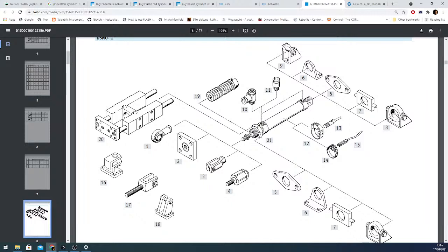Do we need those? Do we need an extra sleeve on the cylinder for dust protection? What kind of couplers we are using for connecting the piston rods? Do we need ball bearing variation for the connection? Do we just use a flange here, or cylindrical mount here, or straight mount as this one?